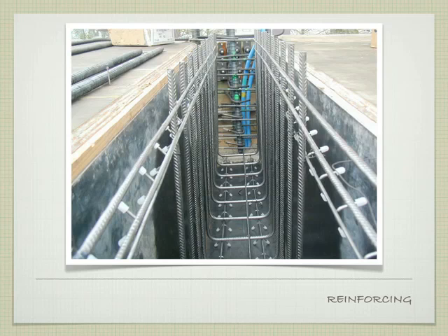No, it refers just to the fact that you have two lines of support and the slab spans in between. So in this example, the lines of support that would make this a one-way slab would be this girder and the girder over here. And the slab spans between girder and girder. Exactly. So we have one line of support here, one line of support here, and the slab is going to span between those two lines of support.